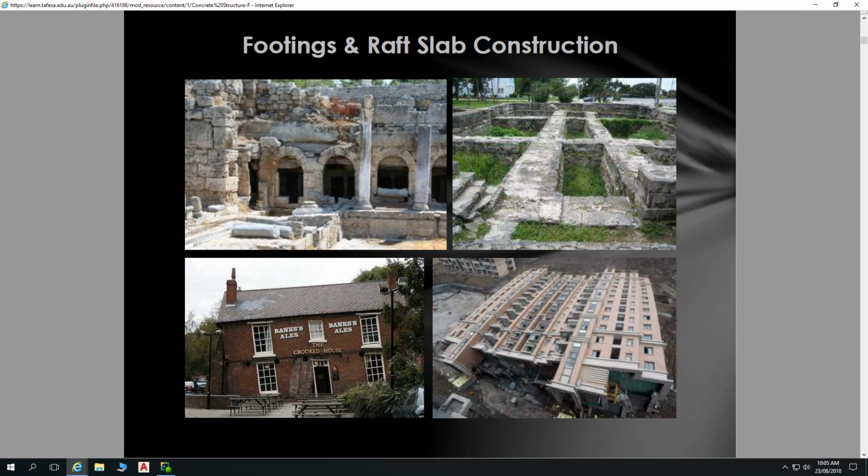But of course, there are many different mixing ratios for various different strengths and slumps, and many different additives that we can also add into our mix to get different performance and different qualities out of that concrete. So with our concrete, certainly not all concrete is the same. We have concrete of different strengths: 20 MPa for your standard slabs, 32 MPa for higher concentration of loads and polishing, etc.